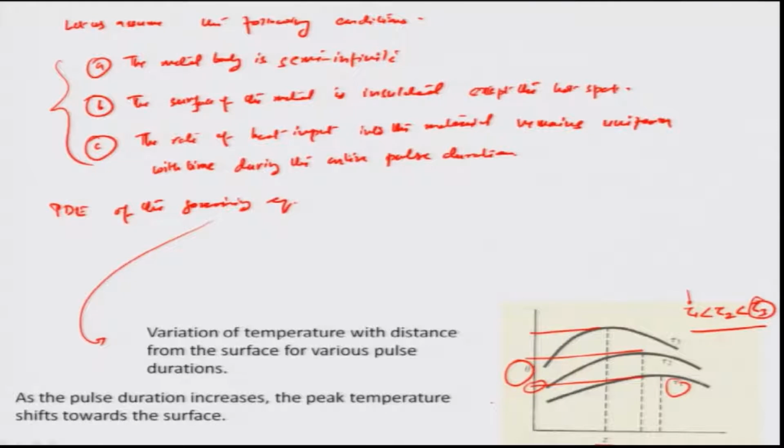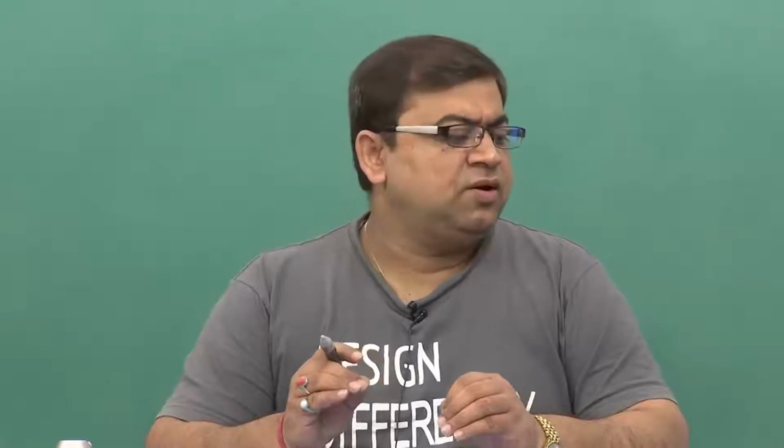And also the very fact that if the time duration of the beam pulse is more, you have the maximum temperature or the maximum hot spot which reaches within the material at a lower value of beam depth in comparison to that of lower value of pulse, because obviously it is a conduction process, and you can think of it that the material is conducting out in an outwardly manner from the vapor pocket which has been formulated, and if supposing the duration of the beam is more, then probably the heat conduction time given to it is very high in comparison to a single small pulse of the beam.